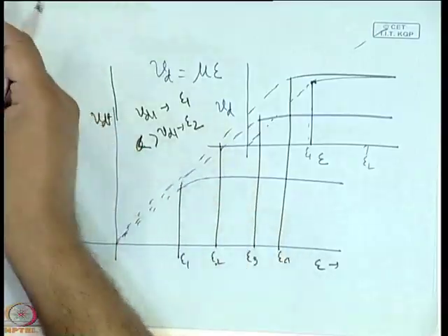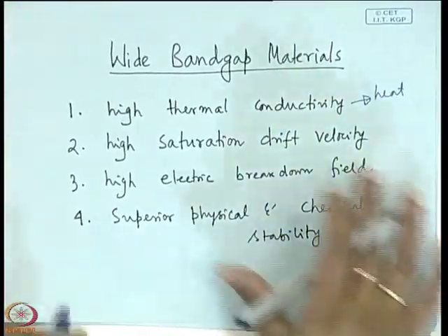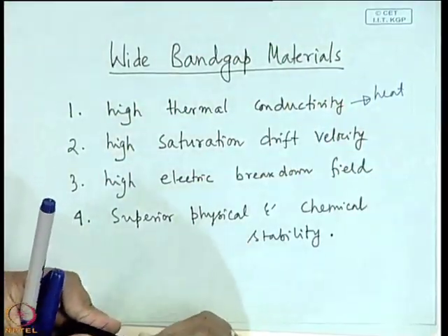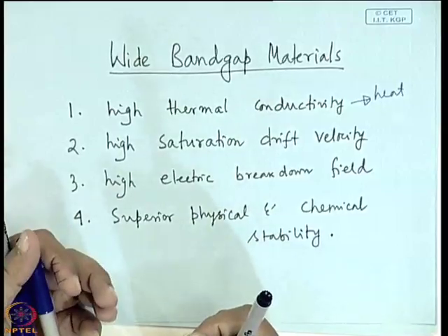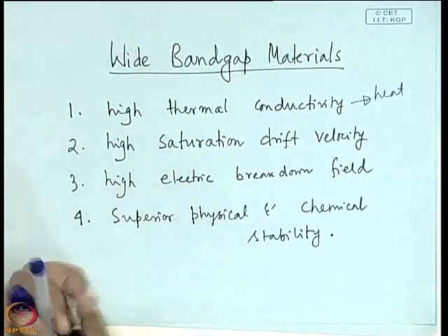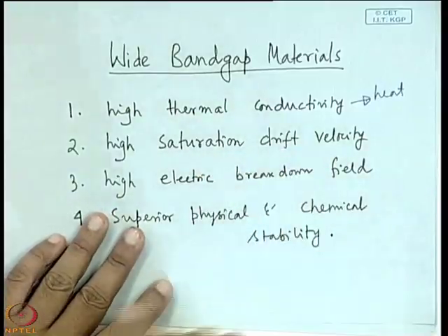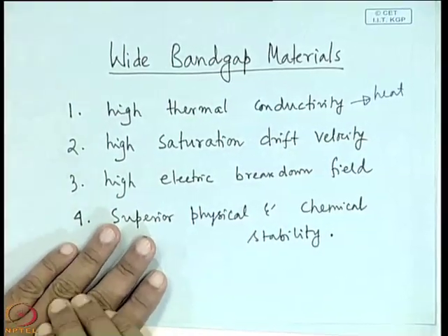Remember that this wide bandgap material is used for high power devices, high power transistors, in electrical devices. Another important aspect of this saturation drift velocity is high frequency application. That means say RF, if you would like to make an RF amplifier, radio frequency amplifier, or microwave sources, then the saturation drift velocity must be very, very high. Otherwise the operation has a frequency limit.